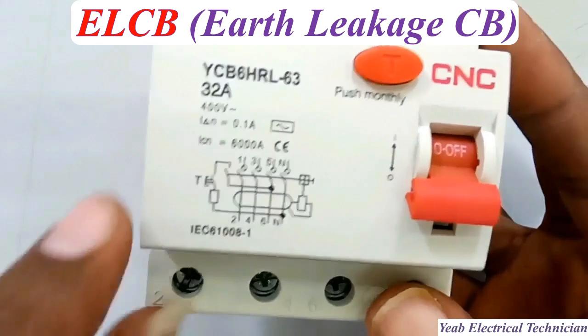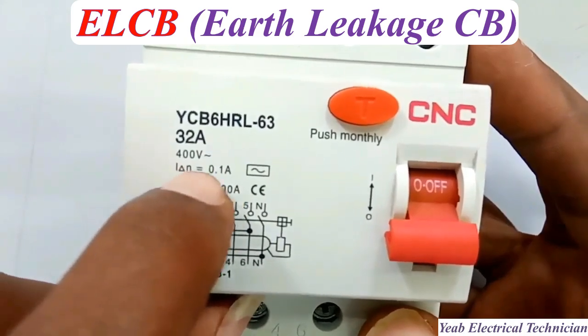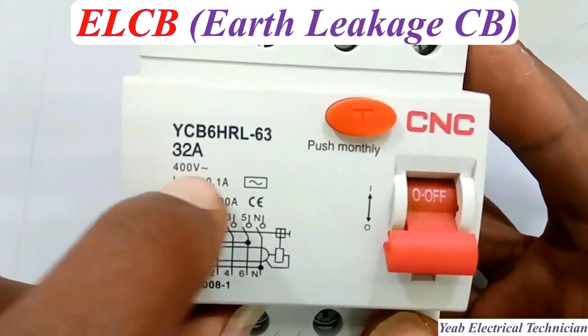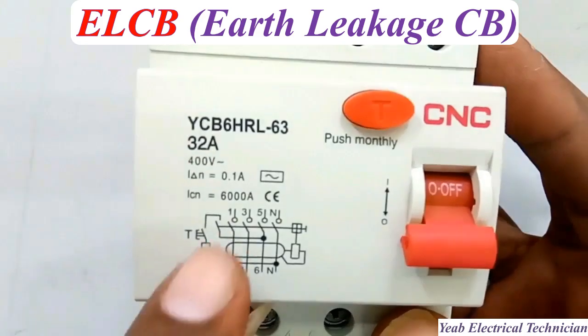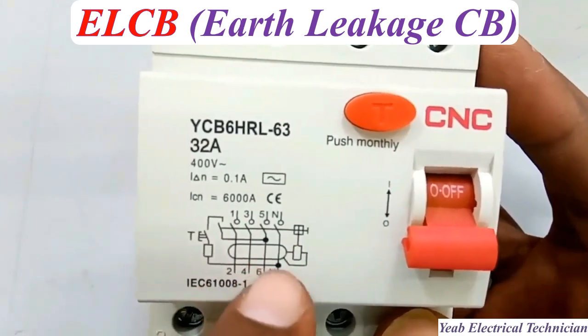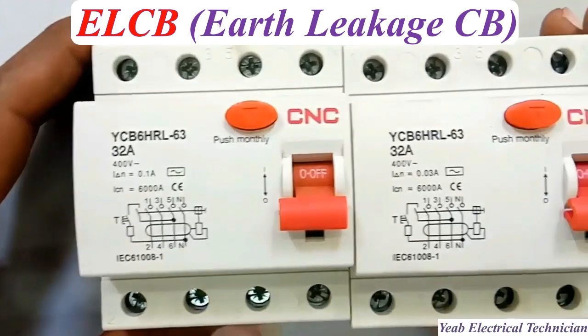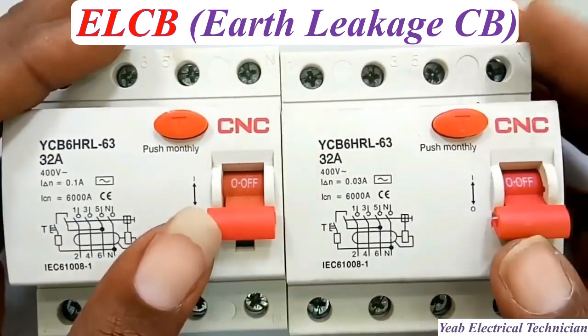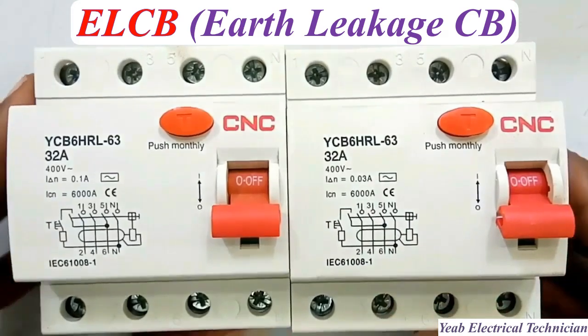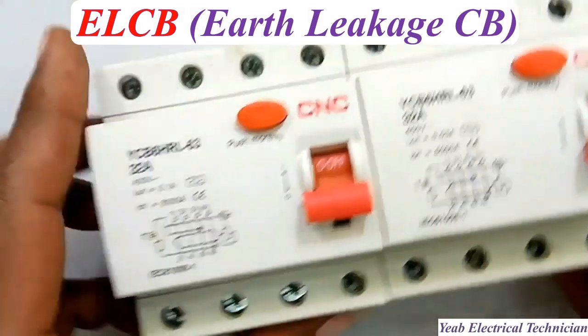In a healthy circuit, the current flowing back through the neutral wire should be equal to the current flowing out through the live wire. If the ELCB detects an imbalance, it means current is leaking to earth. It then automatically trips the circuit, cutting off the power supply to prevent electric shock and potential fires. After tripping, the ELCB must be manually reset to restore power to the circuits.